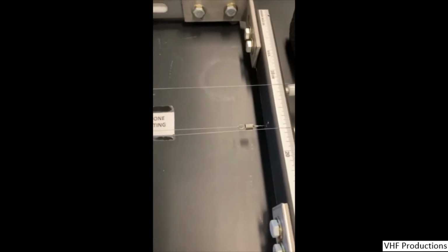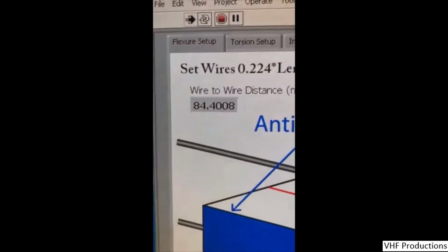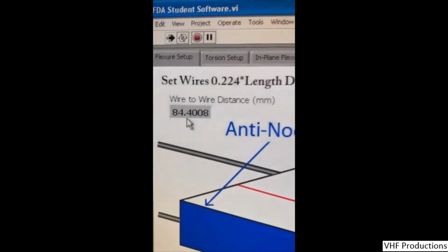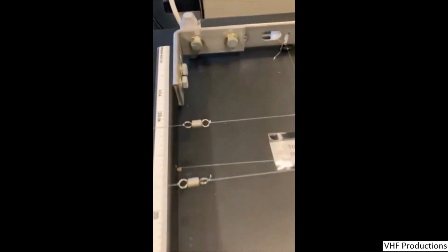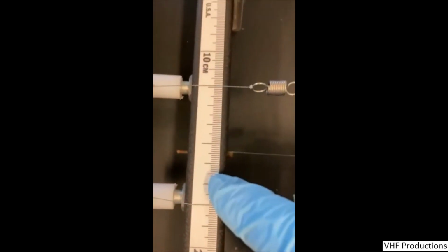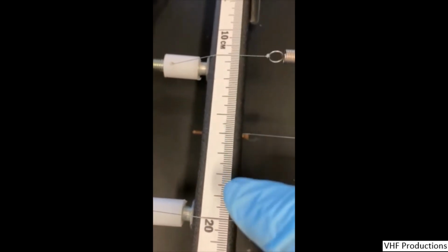We then pick that acoustic signal and we convert the amplitude versus time signal using a Fourier transform into the amplitude versus frequency spectrum. Then, using the software tool, we find the frequency associated with that peak, and that frequency defines the frequency of the first mode of vibration of the plank. From that data, we can calculate the elastic modulus.